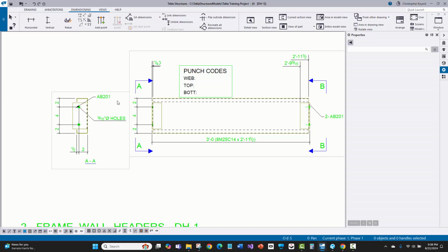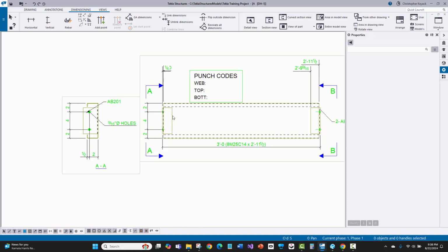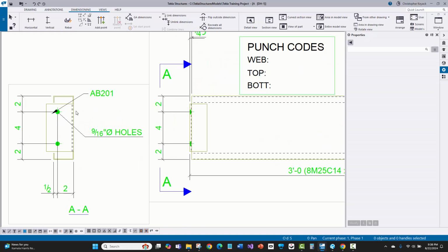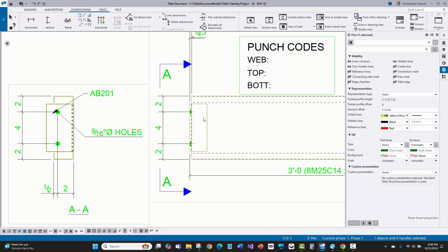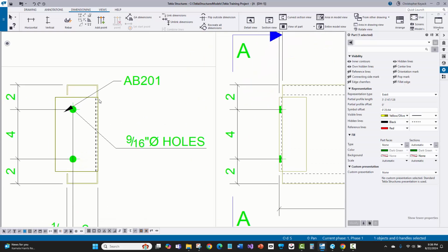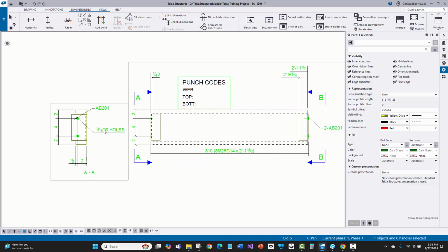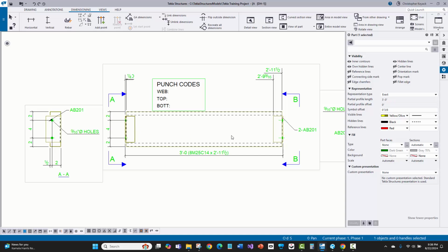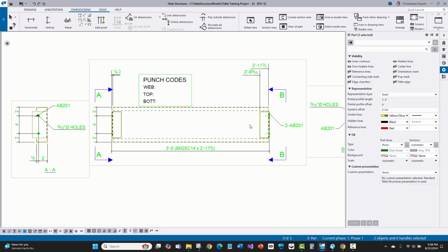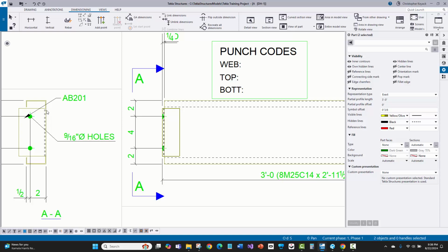It's a little bit misleading what's going on here because I can see that this is drawn, and when you look at the section, the clip is actually supposed to be far side, but because the MBS and SlideRule is bringing this into the Tekla model as flush, and I think they do this for dimensional purposes, for the running dimensions on the jambs for where the holes are located and the opening size. But it's a little bit misleading, and this probably needs to be changed to a hidden line.